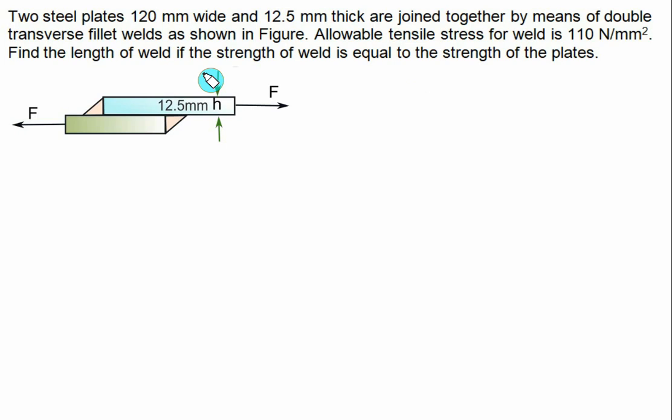You have to find out here first what is the strength of the plate. For that, he has given the tensile stress. So the strength of the plate will be equal to the width of the plate multiplied by the thickness multiplied by the tensile strength of the plate.